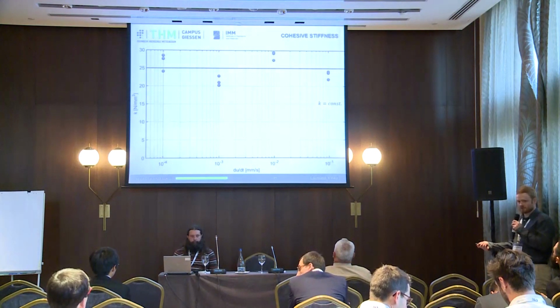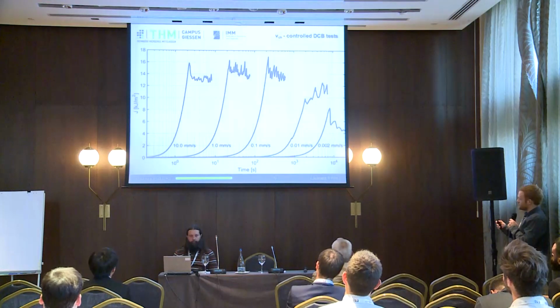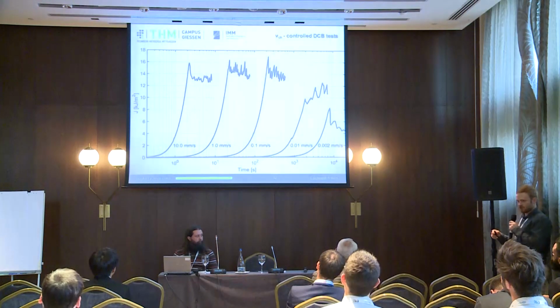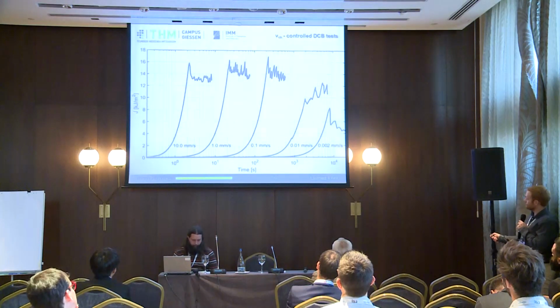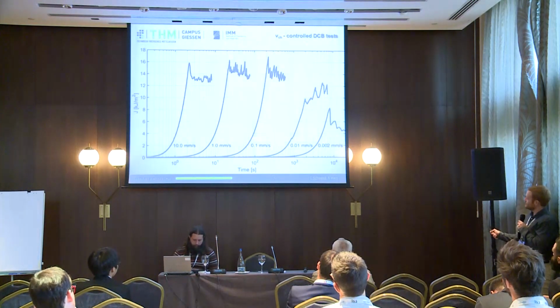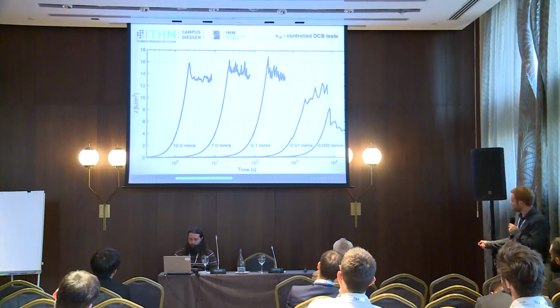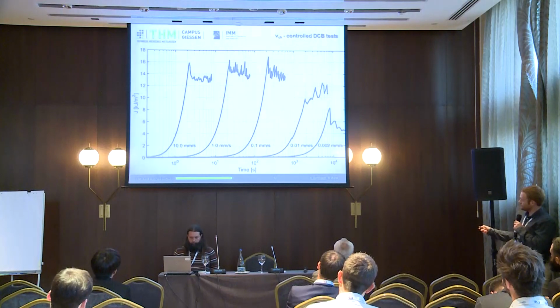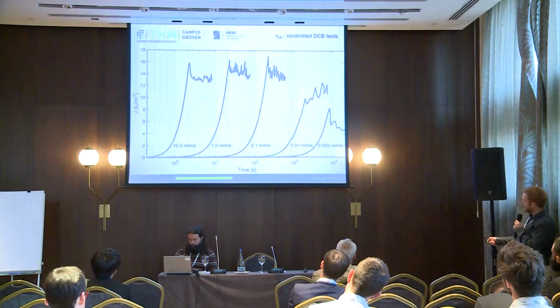So we now have the traction separation law together, which is rate dependent. And we are now changing the controlling of the testing machine from controlling on crack opening velocity to controlling, as you all know, on constant crosshead speeds. You see J over time, different test speeds, and now the curves of J are plotted until the specimen is completely damaged.